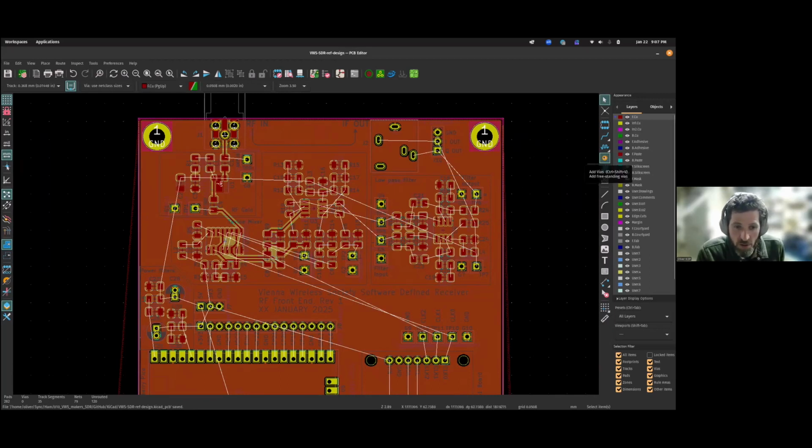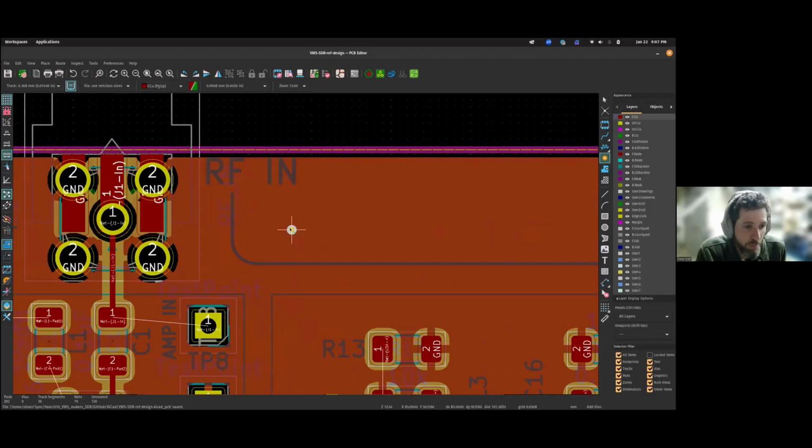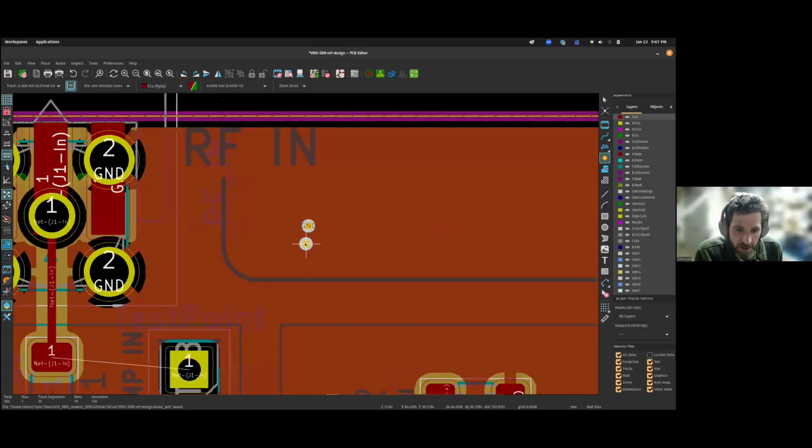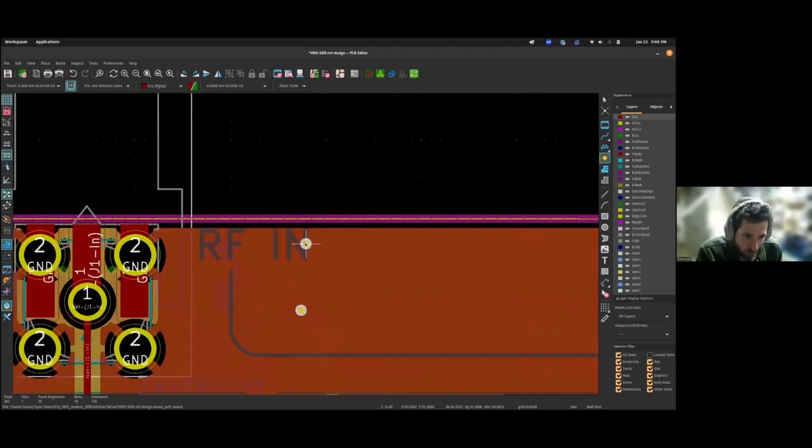Here on the right is a button for a via. A via is a little hole drilled through the printed circuit board that's plated, so it's got copper, like a solid conductor going through your circuit board. If I select that and place it somewhere on the board, I'll zoom in now, you can see it's a ground via. This is now an electrical connection between all the copper layers of the board, all the ground layers, all 4 layers. This is now an electrical connection between them all.